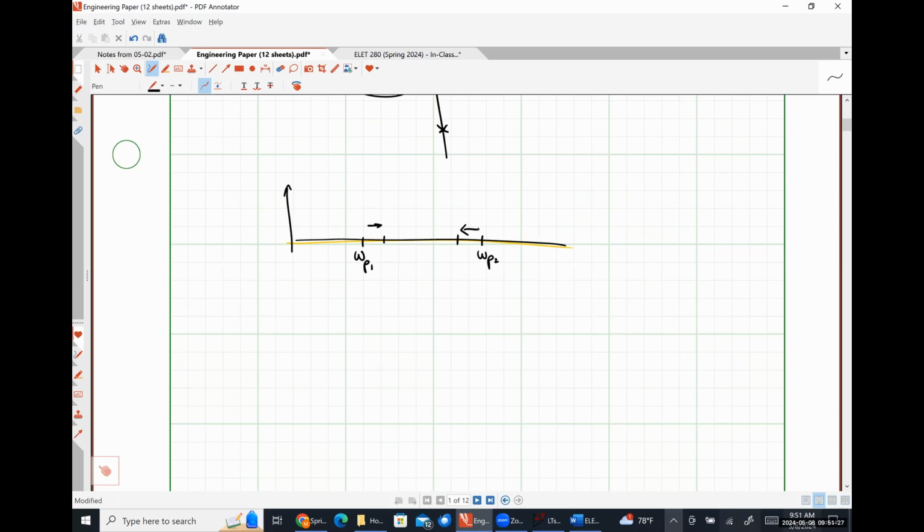So I don't know how it could be any easier than that. When you're looking at the third problem with the MOSFET, you could take the time to actually look at the resistance that each capacitor sees, or you could literally use the exact same relationships. So for instance, the capacitance C pi is analogous to the MOSFET capacitance CGS. So it's going to see roughly the same resistance, except that everywhere that you see R pi, treat it like an open circuit.